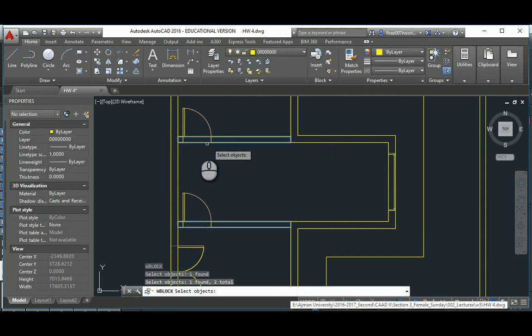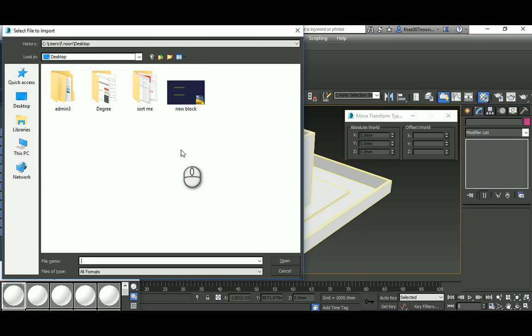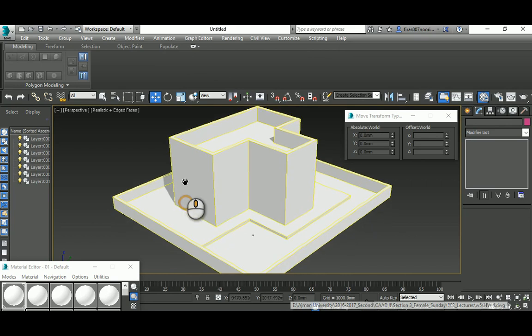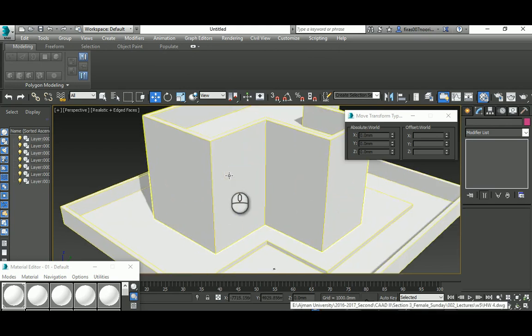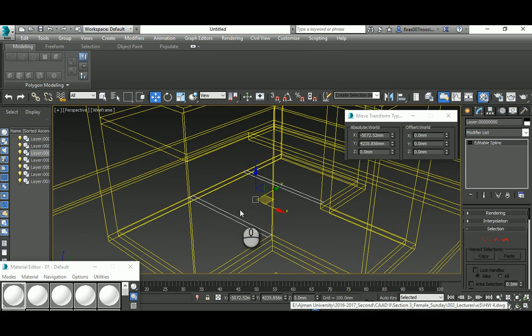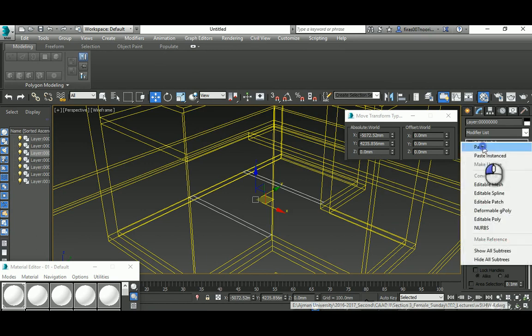Ignore the existence of door openings for now, and then import them here. Now I can see them because they are inside. It's okay, just hit F3 to get the wireframe mode. They are here. They should sit exactly based on rule number 3, the Z value on the ground floor finish in AutoCAD, which is 0. So another happy coincidence. So paste that.